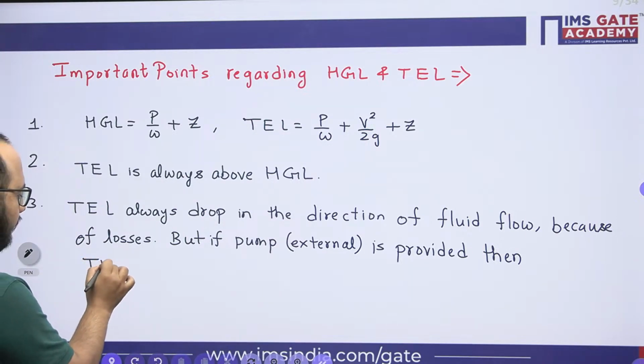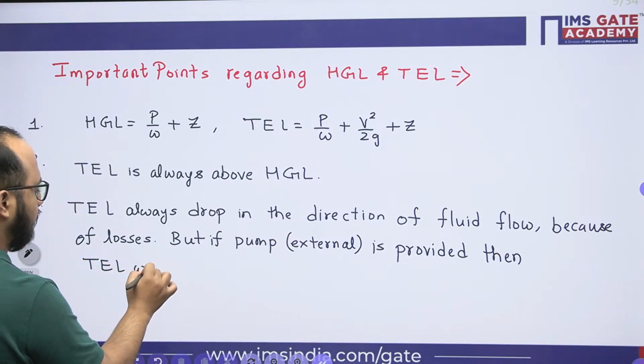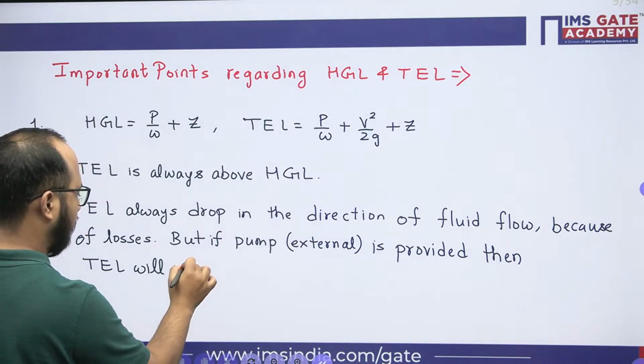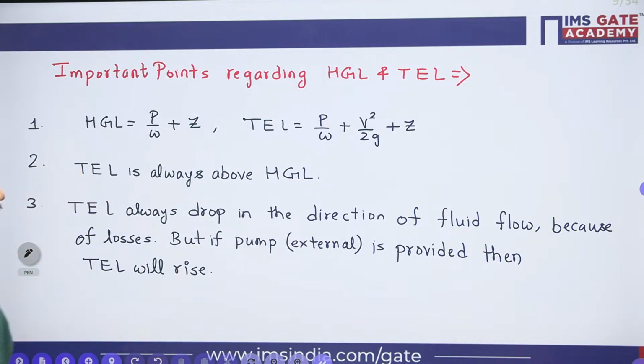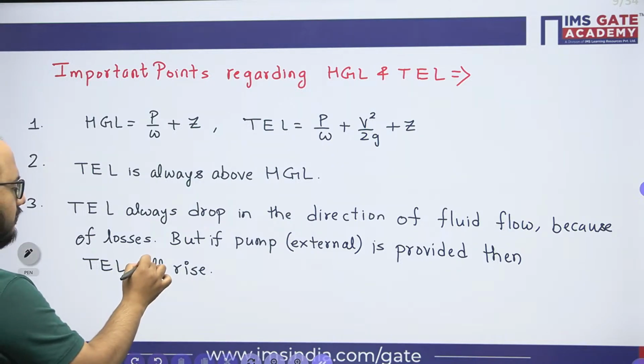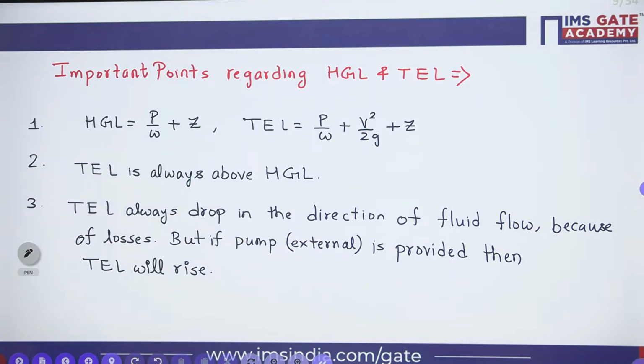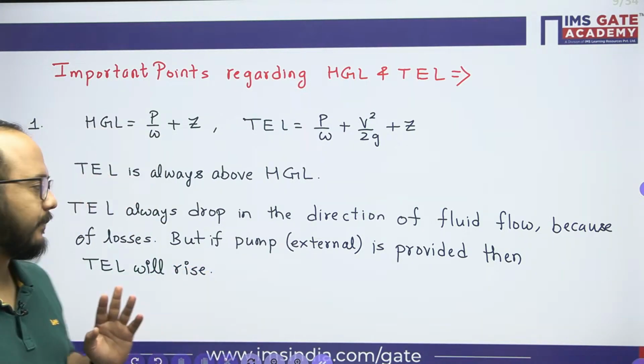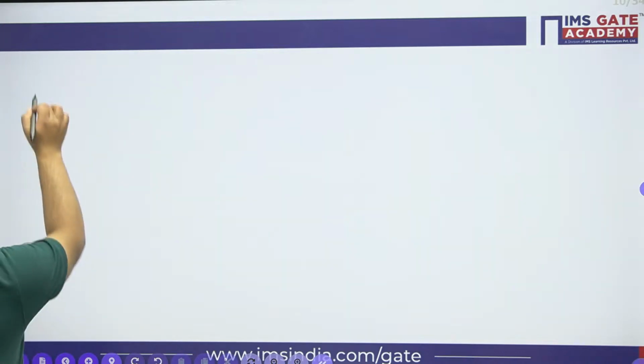TEL will rise. Okay. I hope the point is clear. TEL always drops in the direction of fluid flow because of losses. But if a pump is provided, that is external, then TEL will rise. That is the only possibility. Okay. Now next point.